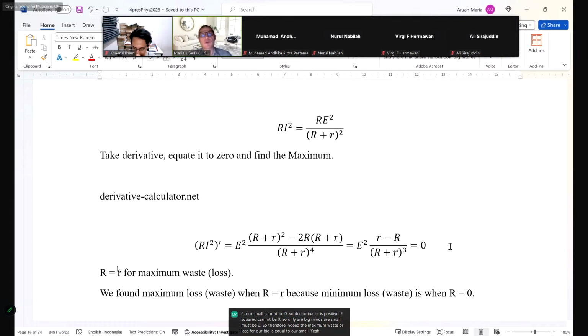And for some people, it's very confusing. They may say, oh, how can that be? Why not half of R or like 2R or something like that? No. The internal resistance of the electromotive force source is a fixed number. We cannot change that, right? So for example, your battery has a fixed internal resistance of R small. But we can vary R big.